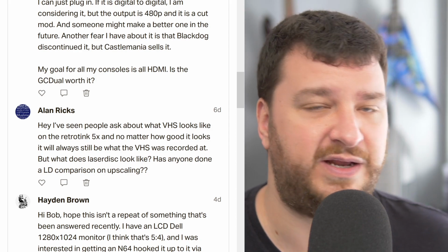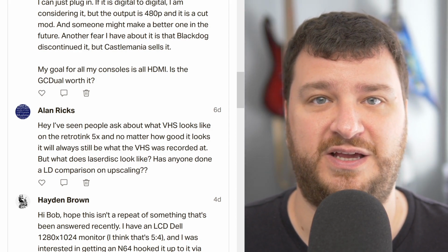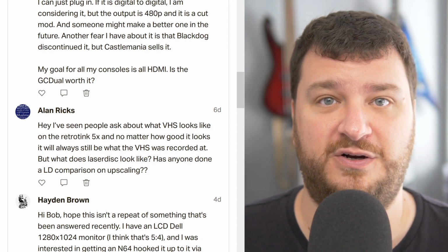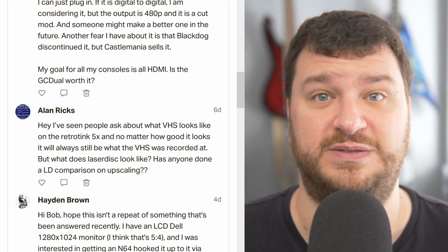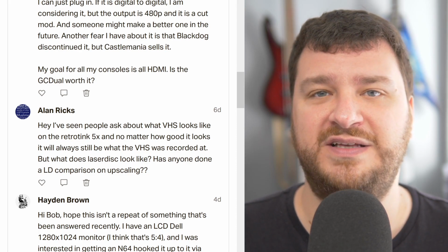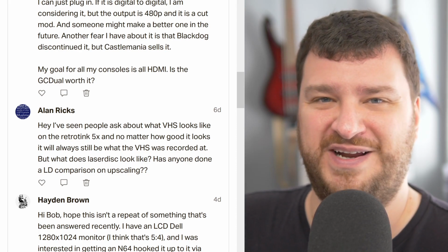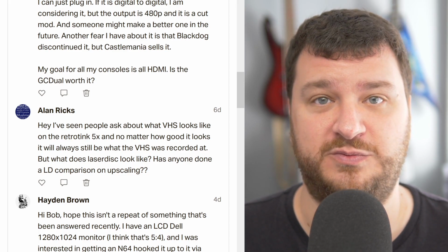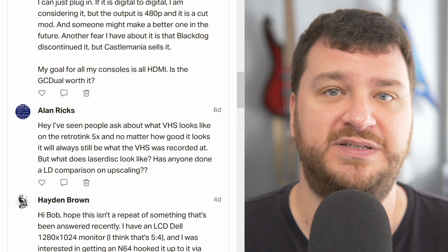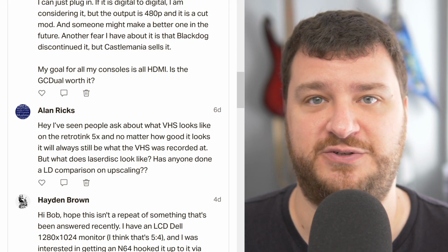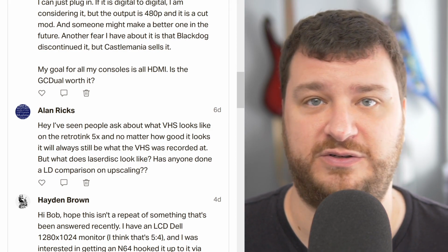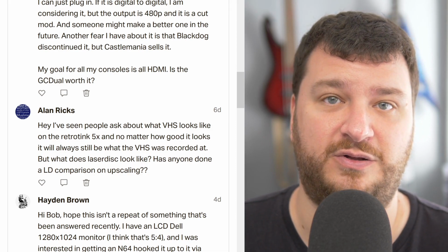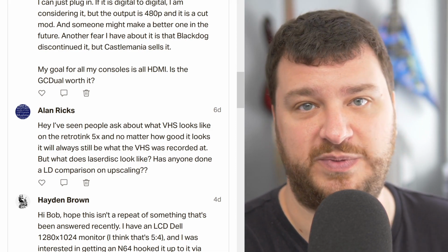I mean, if you could find a 27-inch CRT laying around that only has a composite video input, and you plug in a VCR and a LaserDisc to it, it's going to look awesome. All things considered, as long as their caps aren't all rotted out, as long as the TV doesn't have crazy burn in, but all equipment in reasonable shape, it's going to look really good, because CRTs don't really care if something's interlaced or not. It draws it the same way and it looks fine. Whereas on flat panels, you have to deinterlace and scale content that was originally noisy to begin with.